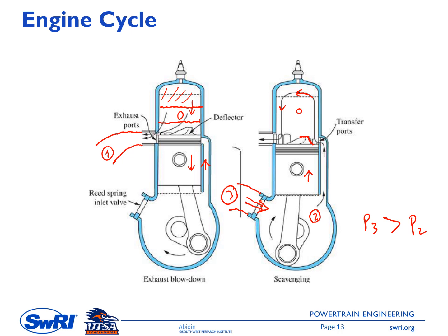Imagine you won't be able to displace 100% of the exhaust gas out of the engine, and the same thing, some of the fresh mixture will flow out of the engine along with the exhaust gas. So there will be a process called short-circuiting. In this case, the fresh air will also exit the engine, and this is a direct inefficiency in 2-stroke engine. If you already have the fuel there, in a spark ignited engine, some of the fuel will exit the engine. Usually the power density is about maybe 10 to 20% higher than the 4-stroke engine.